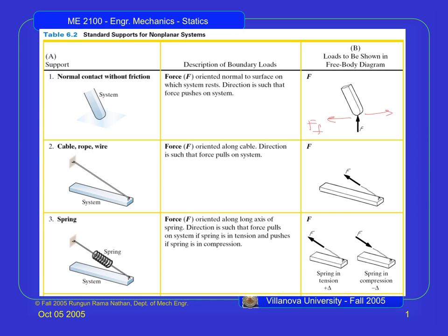So those are just fishing line. And fishing line, though, is also braided, actually. So there are fibers in there that are all woven together. That's literally what you have in a suspension bridge. The smallest cables are like this small, and then those are all braided. Then several of those are braided together until the cables on bridges are literally like this much in diameter. They're huge. It's braided, and then those are braided within others that are braided. The reason for that is it increases the tensile strength in the actual cable. Yeah, the tensile strength is the word.